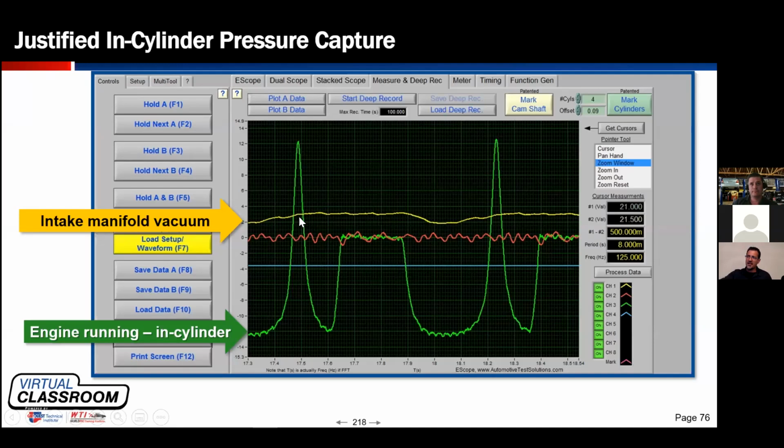Now, the intake trace tells you why. If vacuum goes this way and a lack of vacuum or pressure drops down, do you see cranking? We produce about 3 inches of mercury right here on average. It's pulling, it's pulling, it's pulling. We've got about 3 inches of mercury.